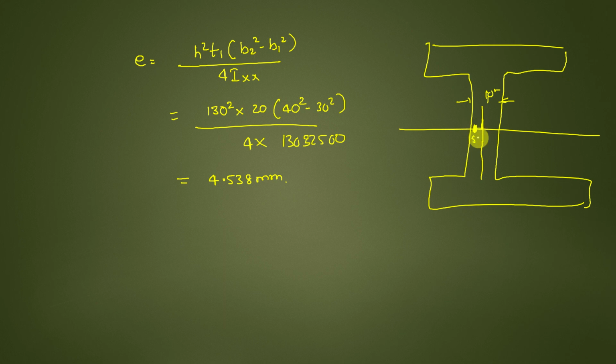The shear center is located inside the section over here. So that means it is subjected to very little torque whatever load you apply on this. If the shear center is away from the axis, then you'll get more torque. Then it has to follow separate design considerations while designing steel structures in design of steel.